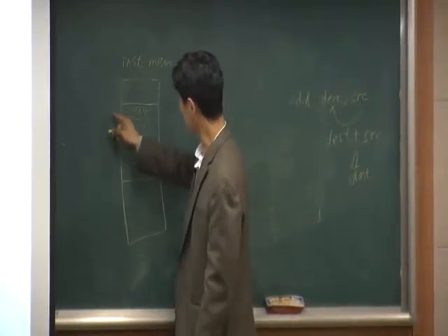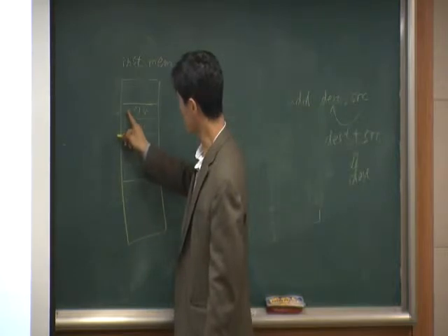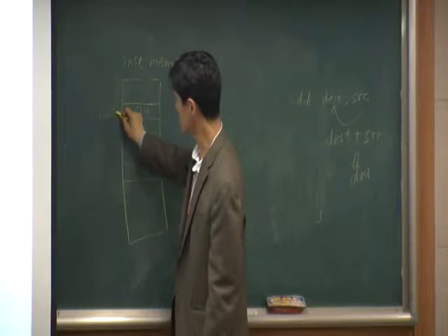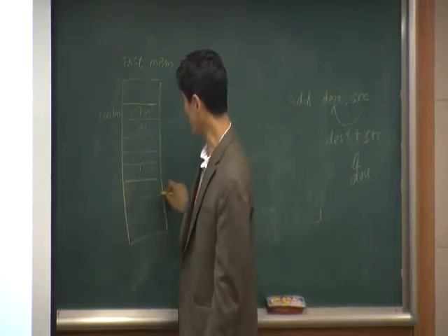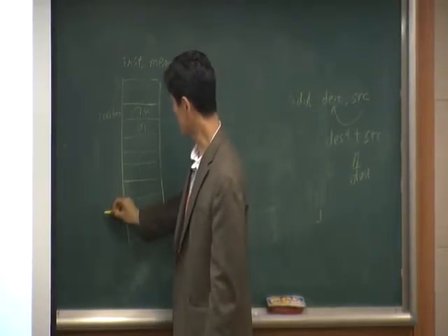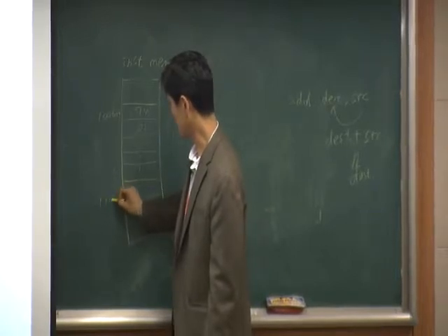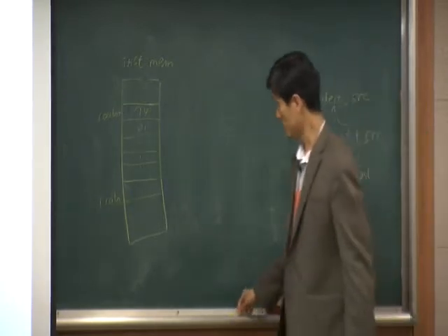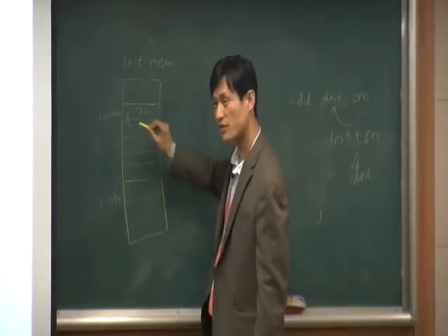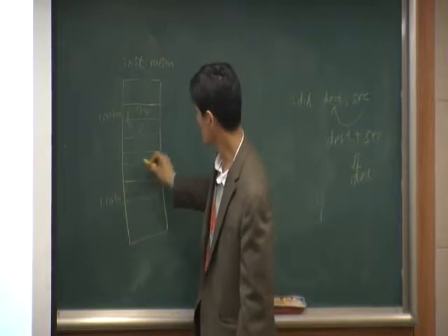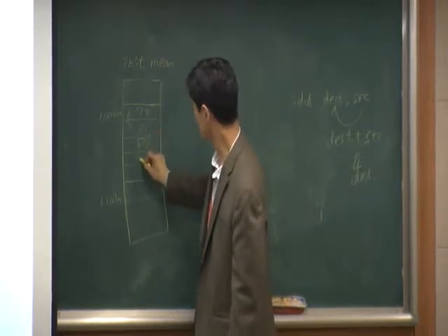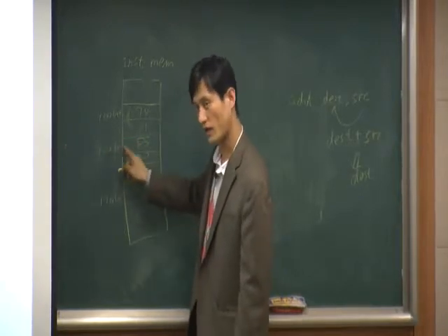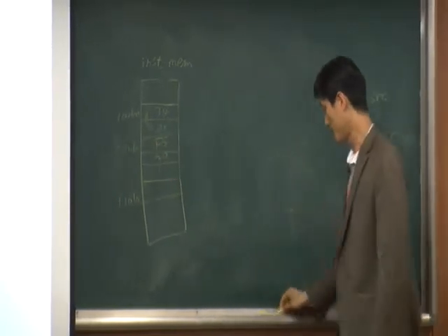Let's say the first instruction has the address of 100H, just as an example, and the last instruction is like 110. These two bytes are the first instruction, and the second instruction is F530. That's the second instruction, and it is at 102H, and so on.